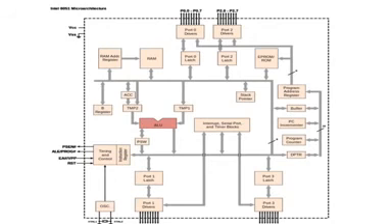Whereas in the serial port, in serial communication, the data is sent 1 bit at a time. The 8051 has one serial port for this serial communication only, and in the 8051 it is full duplex. Hence transmission and receiving are both done simultaneously.